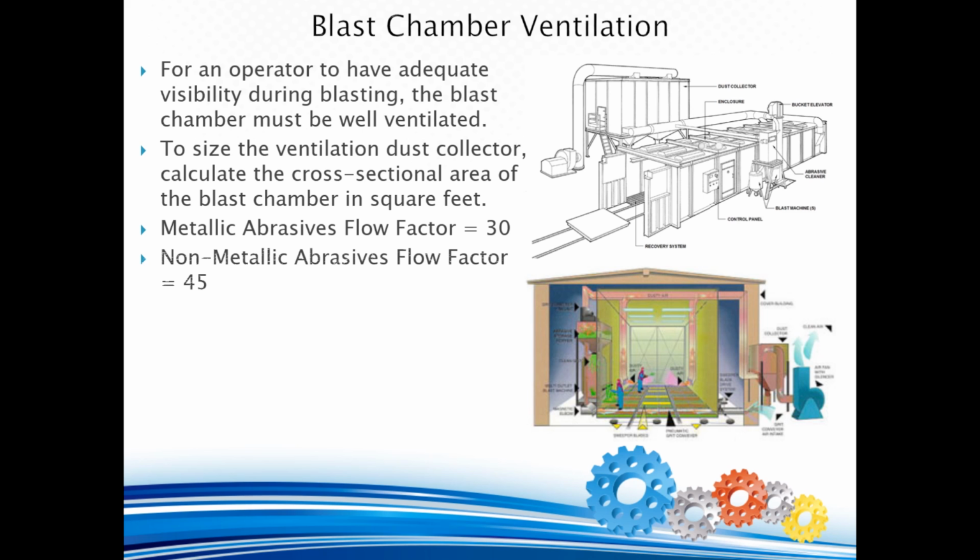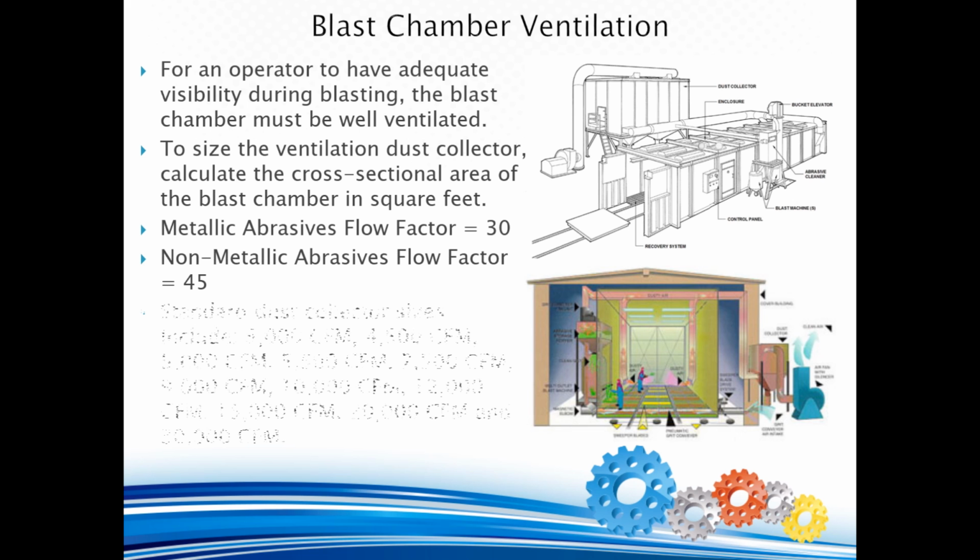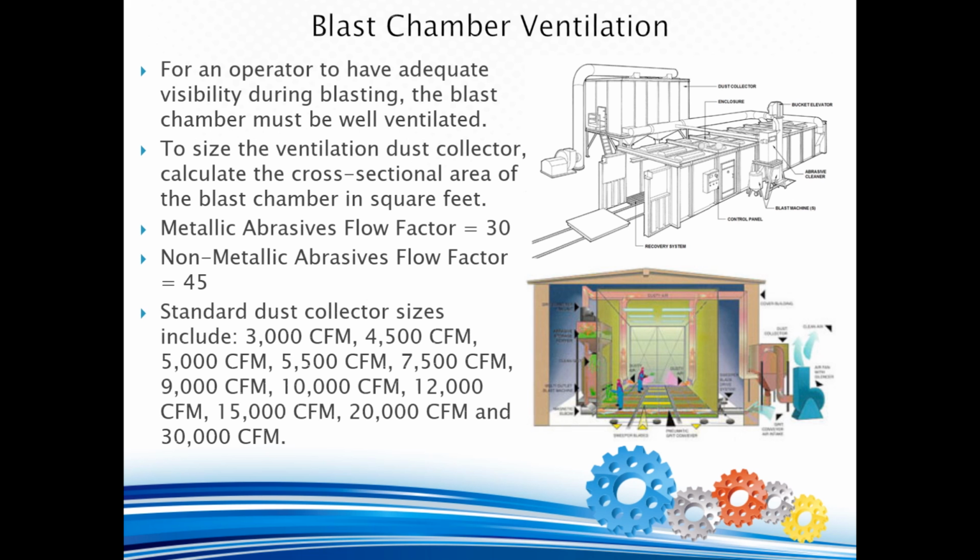It is also important to note that single-use expendable abrasive media such as copper slag, crushed glass or silica sand should never be used in a blast room system due to dust overloading from the high abrasive breakdown rates.